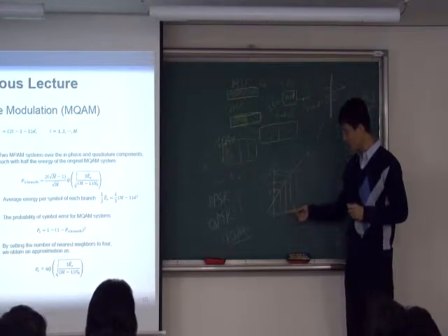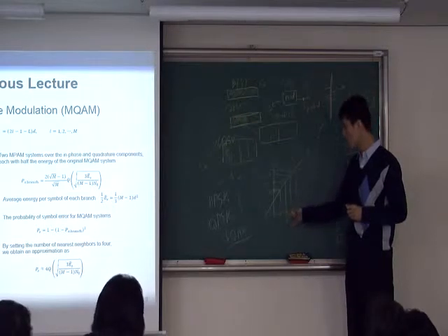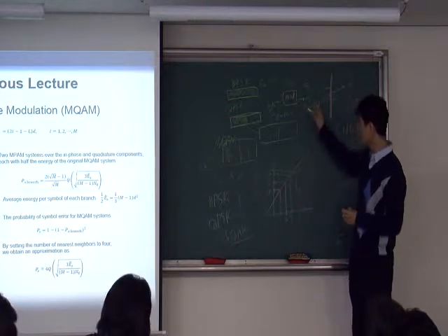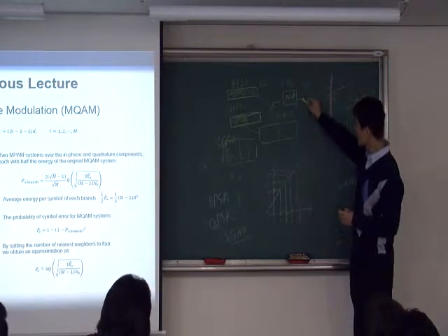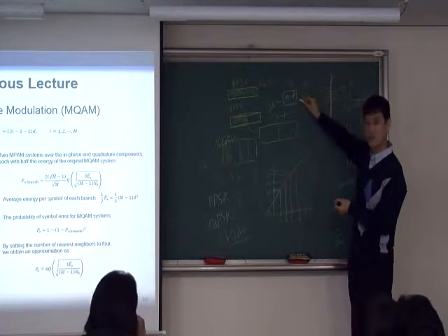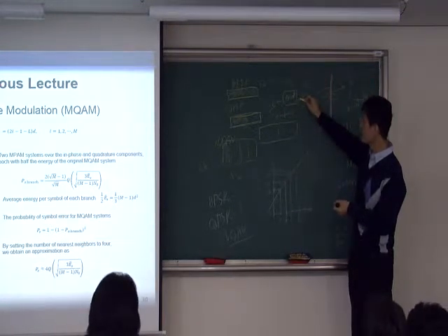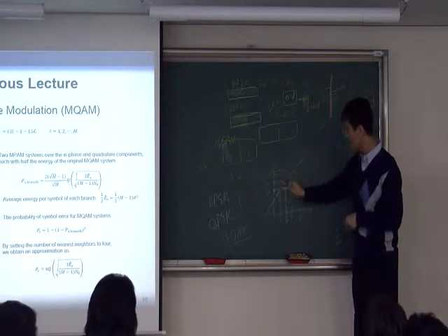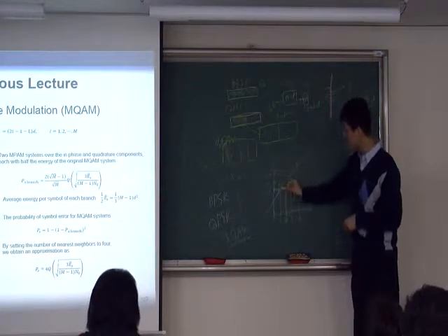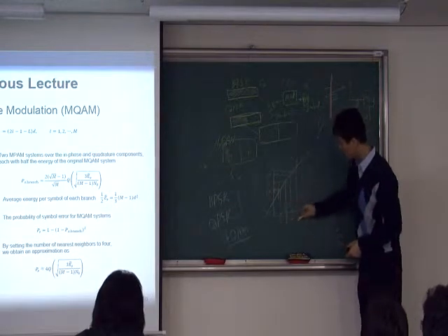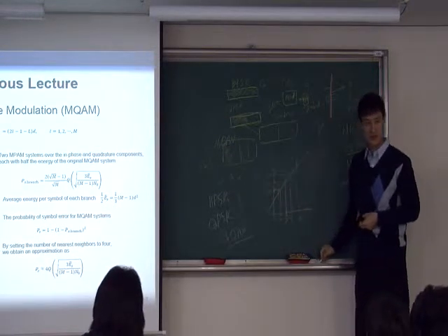If you have to change the symbol energy, then you want to minimize the range. If you have a wide variation in the energy right here, before the power amplifier, you have to minimize the swing range. If you have sometimes too much energy, sometimes too low energy for the power amplifier, that basically means the power amplifier has only this linearity range, but your input is going to swing like this. That means your output will be distorted. That's bad.